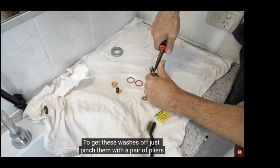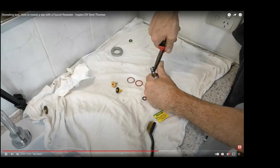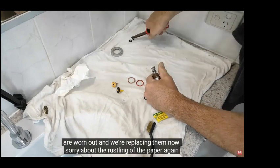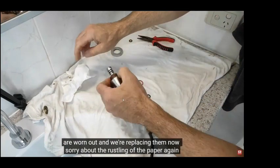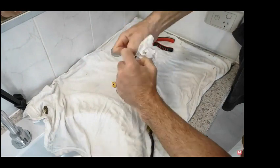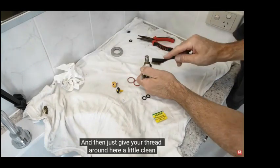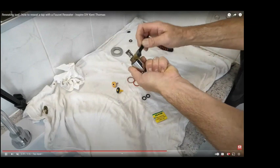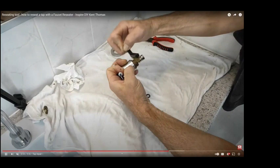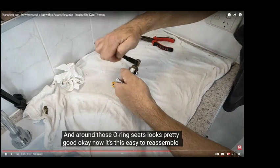Don't do that. What you want to use is just a little electrical-size screwdriver, a real thin, skinny one. They're junk anyway, those O-rings. You could cut them off with a craft knife or something. It's pretty weird to have 2 O-rings on there. You only have 1. You want to make sure they're the right size. I wouldn't necessarily use that, but a rag is helpful. Just clean it with a rag. Slide the new O-rings on where the old one went.